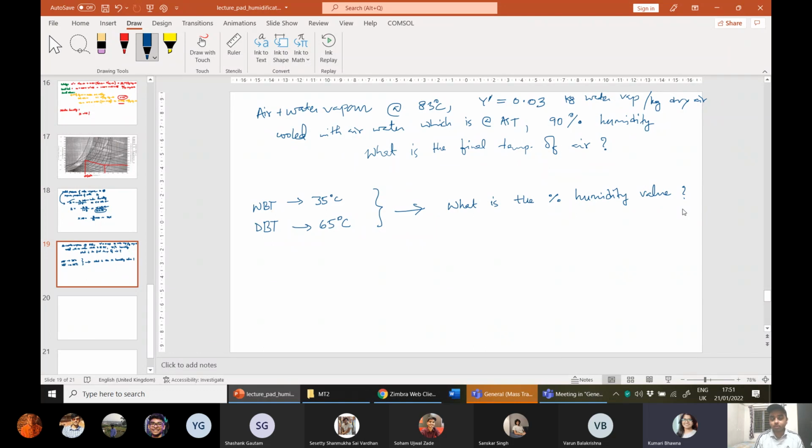do. For the normal air, they measure the wet bulb temperature and the dry bulb temperature, and from there they estimate out the percent humidity value. There is as such no sort of moisture sensor that is used. Right, you get this value from the estimation of the dry bulb and the wet bulb temperature. You work out the humidity, percent humidity, and the relative humidity value.